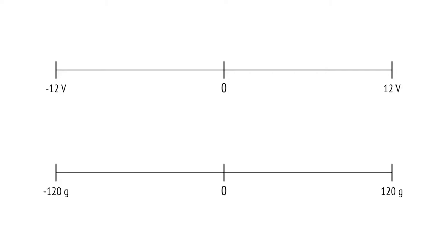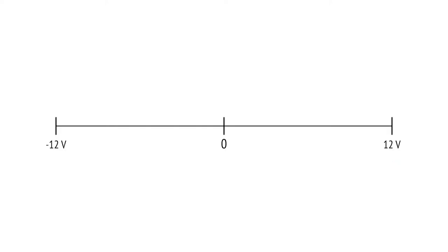When the sensor sensitivity is 100 millivolts per G, then we can operate with plus minus 120 G's acceleration range. If the higher amplitude comes, it is converted to the maximum value. For example, the 150 G's is converted to 120 G's. Now we introduce the key factor of each converter. It is the resolution. The resolution is a number, and it defines something like stripes inside the measurement range.